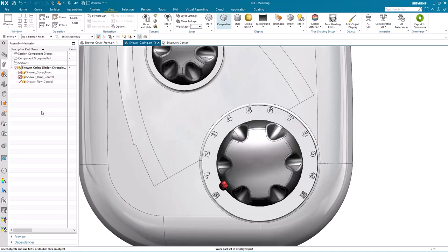So just to recap what you've seen, you saw me create a rule-driven display for a shower flow control which had dynamic content using algorithmic modeling. Within the logic editor environment, you saw how we were able to create the dynamic range, merge lists, and define the equal spacing for the text around the display guide curve. Finally, we looked at how you could reconfigure the automatically generated dialog for the algorithmic feature so that you're only presented with the information that you need to see.